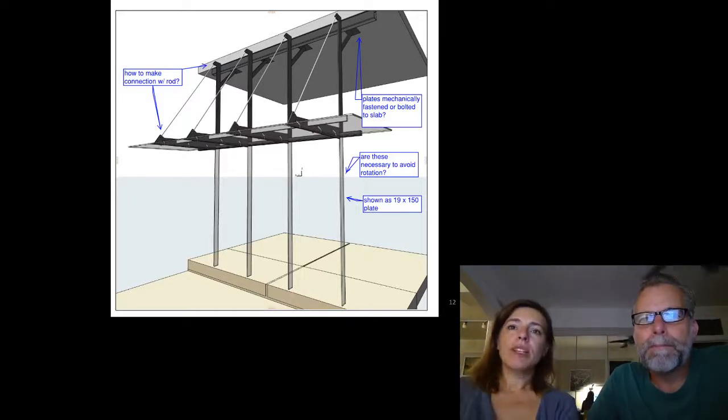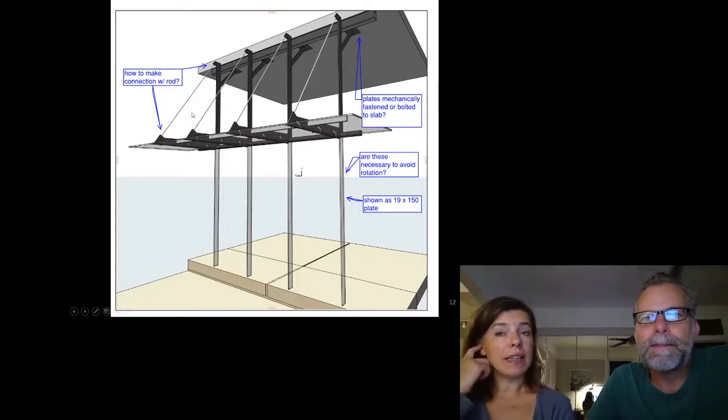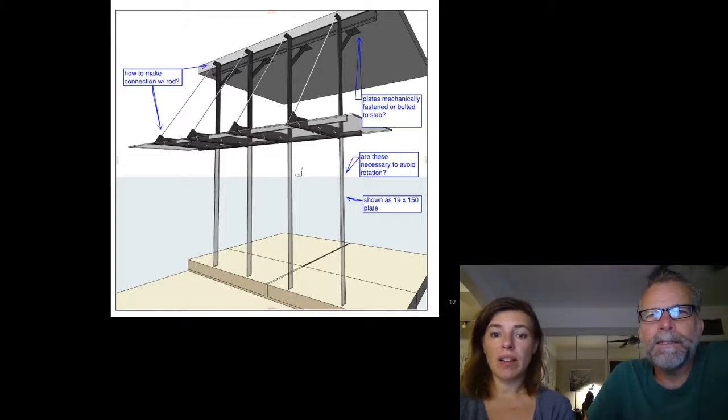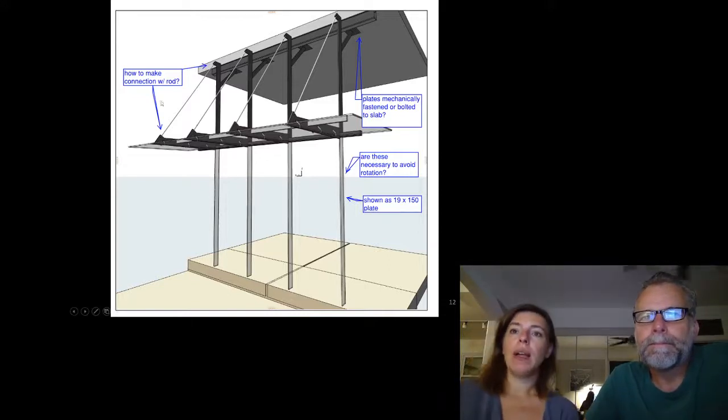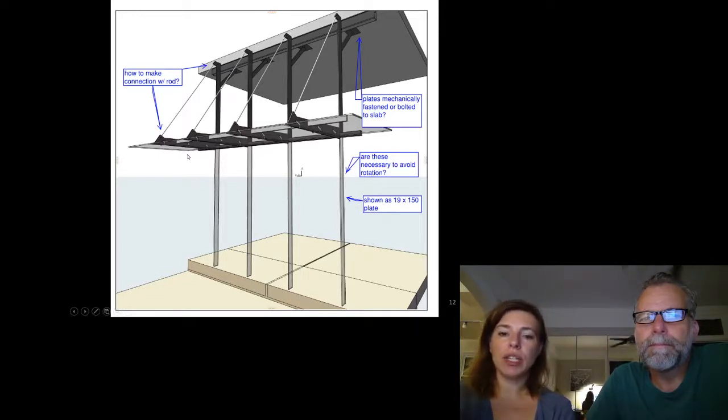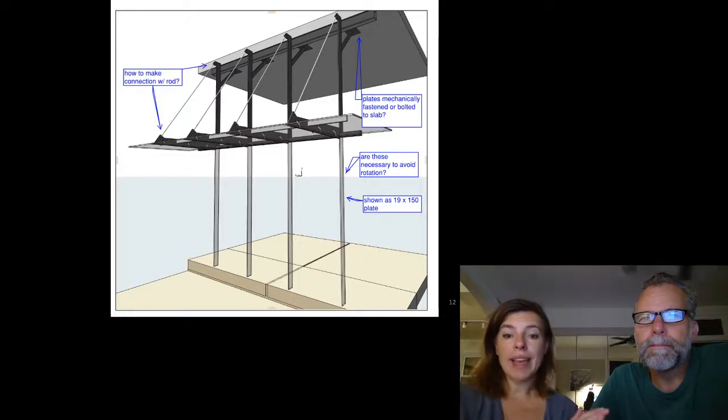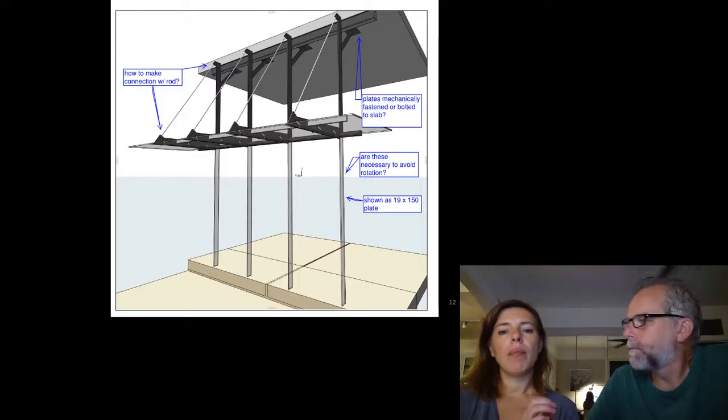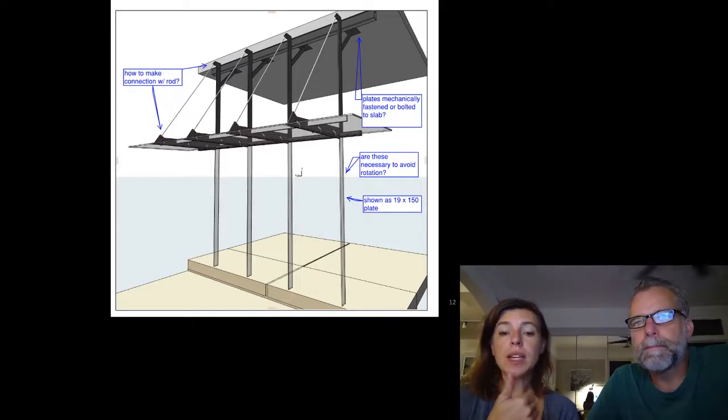But now I've done a few of these recently, and it was dependent on where the snow loads were, that at the worst case conditions, which were the end conditions, because we use a higher wind load at the end conditions, the uplift force really governed.